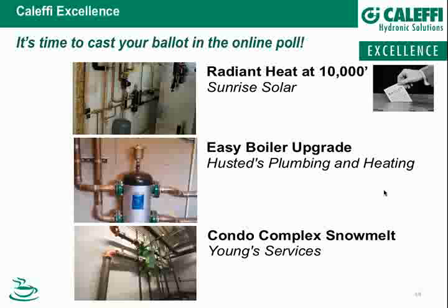I'll point out that if you buy a little watt meter, and you can actually buy these devices called kilowatt meters today, you can buy them online for $25. You could put a line cord on a circulator, plug it in, and operate it at different flow rates. If you had a flow meter in the system, you could actually plot those curves out for any circulator you want. You just need flow rate information and wattage.